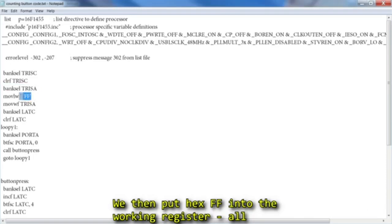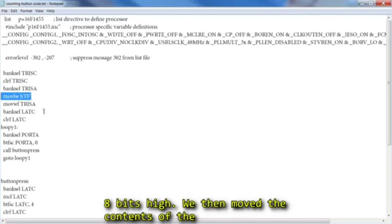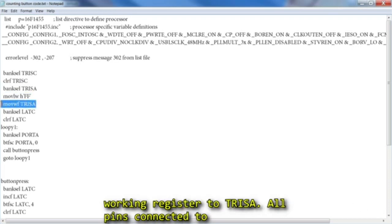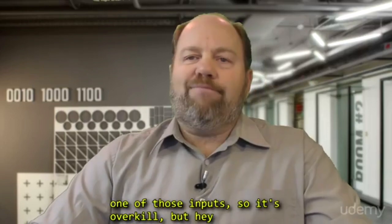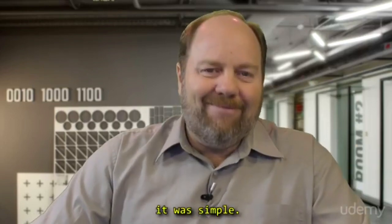We then put in hex FF into the working register, all 8 bits high. We then move the contents of the working register to TRIS A. All pins connected to port A are now set up as inputs. Now we're only using one of these inputs, so it's overkill, but hey, it was simple.